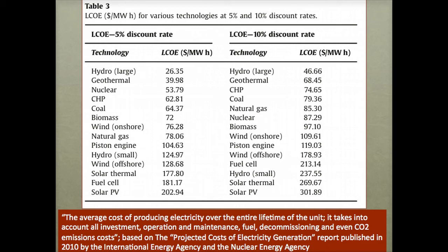Maxim estimated a weighted LCOE average using the nameplate capacity of the power plant as a weight. Nameplate capacity refers to the amount of megawatts or gigawatts the power plant can produce at full rated capacity. Weighting the LCOE by nameplate capacity can generate errors, since not all power plants operate at their nameplate capacity during a similar time period. For example, baseload generators operate at the nameplate capacity more often than peakers or intermittent renewables, which translates to different maintenance and operating costs among even otherwise identical units.